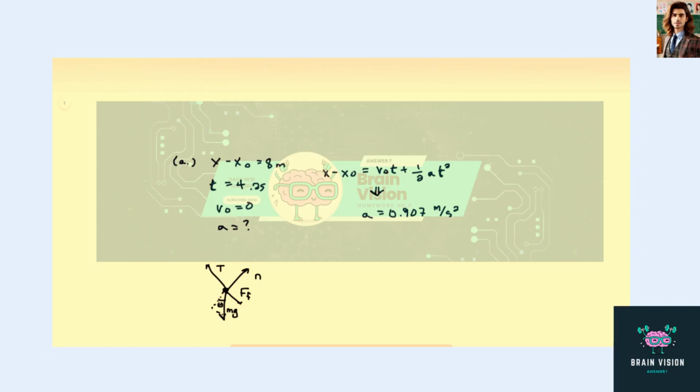Now, from Newton's second law on the y, we get that the normal force is 16,090 newtons. And this tells us that the friction force is equal to the coefficient of kinetic friction times this. And we're given the coefficient. So multiplying that through, we get 5,702 newtons.